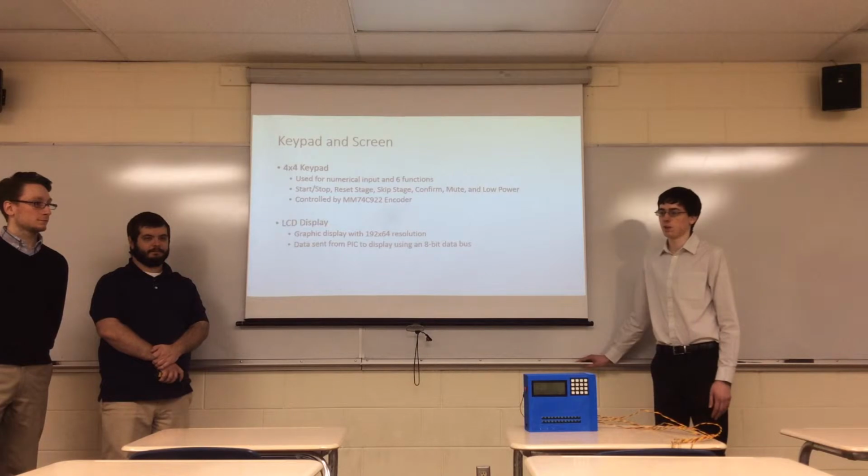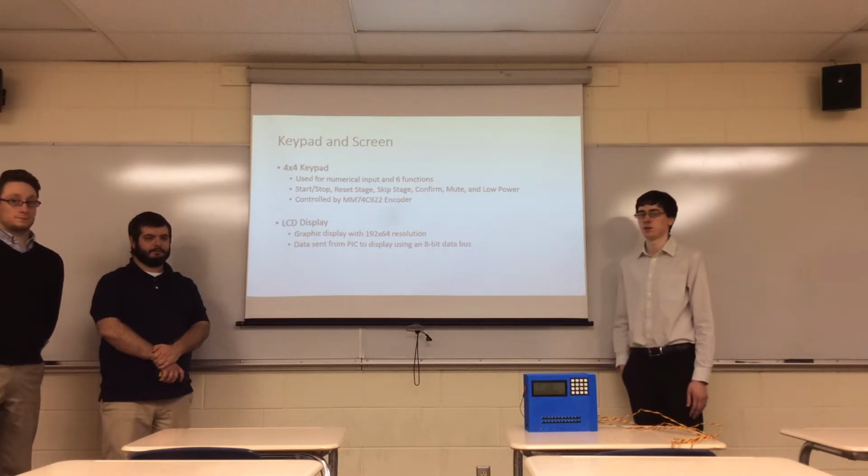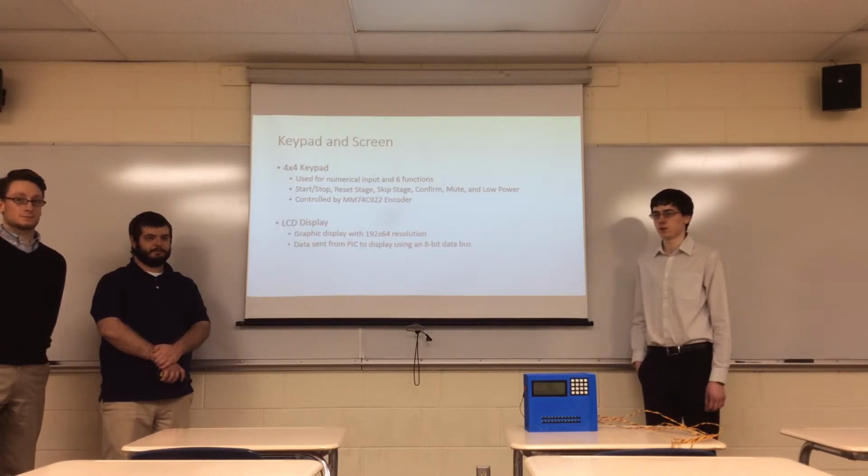Our keypad, we send it through the MM74C922 encoder, which allows us to convert it into a binary value without having to use too many pins or constantly cycle through rows. For the LCD display we use a graphic display with a resolution of 192 by 64.